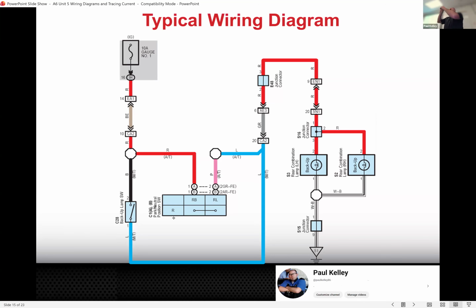Typically about that big. The manual one's going to be like this. It's just going to be literally screwed into the case. The reason that the neutral safety switch is a little bigger is because there's probably about 6 to 10 wires going through there, because there's a circuit for telling if it's in park, a circuit for telling if it's in neutral, a circuit for telling if it's in reverse, and then typically for drive and any of the lower gears, so that way it can tell what your shifter position is. On a new car, they'd most likely call it the range switch.